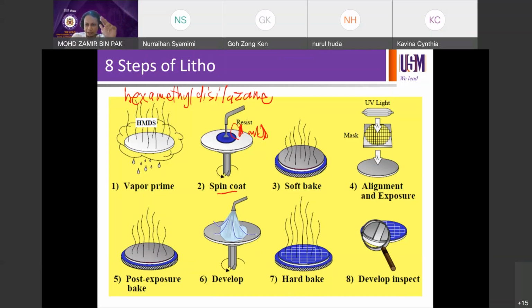So to apply the right voltage to the right side, you have to have a metal contact. So metal contacts from this point onwards are classified as back-end processes in a front-end fab. Okay? Remember that? Not everything in it is front-end. So we have processes in the front-end called front-end, and we also have processes called back-end processes.